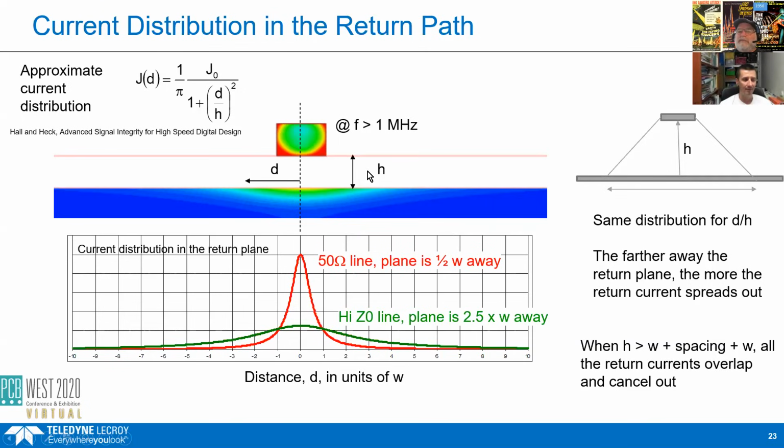And if that same return path is shared by another conductor, like I have another conductor here, and I cut this return plane so that I make the return plane over here, and I have another conductor over here, and his return current is in this region, and his return current is in this region. If they share, so if I screw up the return path, so I increase the inductance, and I share that same return path, then this poor little guy sitting here is going to see all the extra voltage noise from the aggressor's DI/dt through that extra inductance, and he's going to see that as part of his voltage noise.